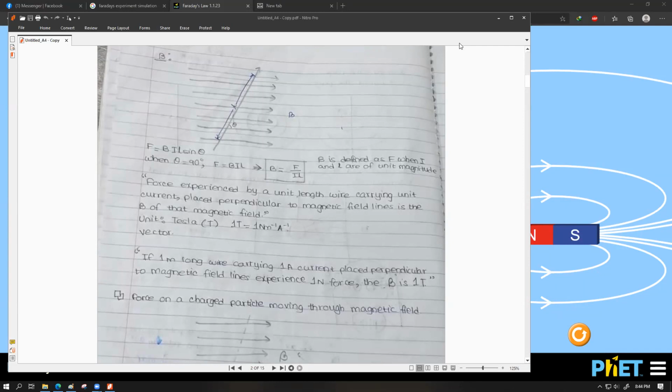If you change to a bigger or thicker wire or a thinner wire, you will be affecting the resistance of that conductor. So we need to control the voltage applied across the conductor in such a way that the current is maintained at 1 ampere. It is the current that we are trying to make fixed.